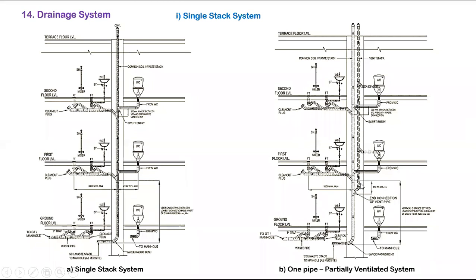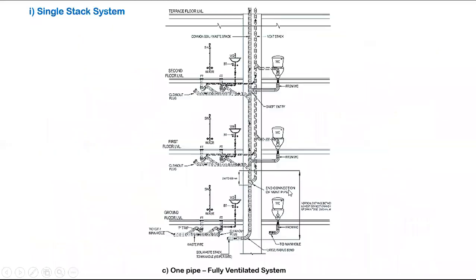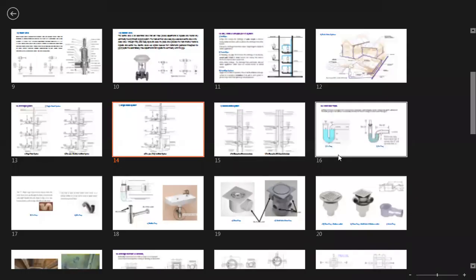In addition, at the ground floor we are providing a vent for the soil stack also. This is the single stack system, fully ventilated system.